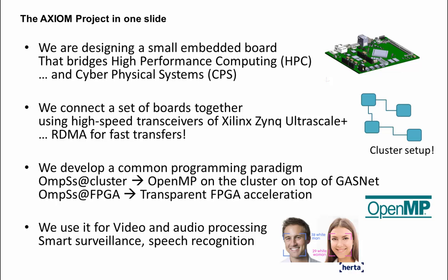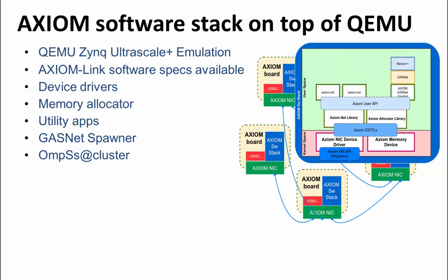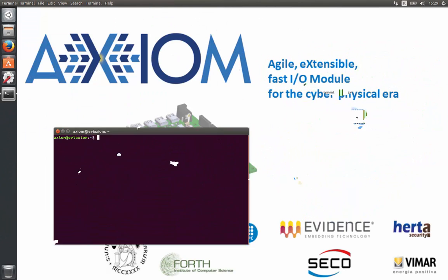processing application use cases. In this video, we will emulate the cluster configuration using QEMU virtual machines, which will emulate the Zynq UltraScale+ nodes of the cluster. The QEMU virtual machines are connected together using a virtual switch that is used to emulate the routers implemented in the Zynq FPGA. The software used in this video has been packaged in a VirtualBox virtual machine to ease its